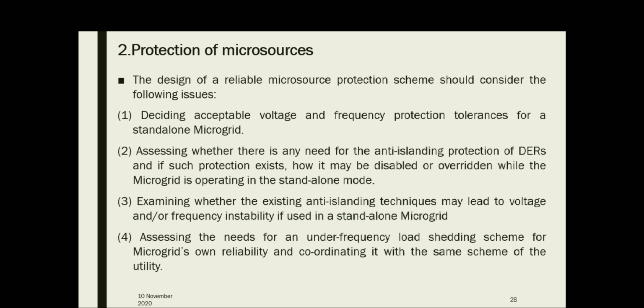And the protection of micro sources. The design of a reliable micro source protection scheme should consider the following issues, and extensive dynamic simulation studies should be carried out in order to address these issues. The issues are deciding the acceptable voltage and frequency protection tolerance for a standalone microgrid.